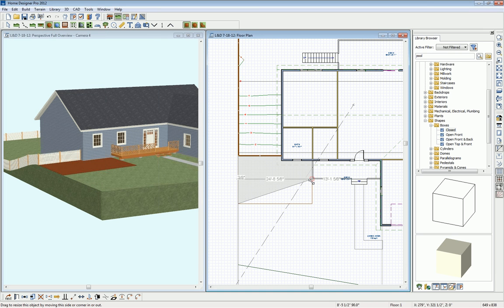And then I'm just going to modify a few different options here and select our edge and curve it with our line arc tool. And then we can also change that arc. So to change the arc freely without any snapping, just hold down your control key on the keyboard and that will temporarily eliminate any snapping. So now we have our garden bed.